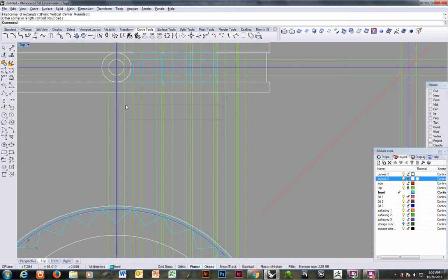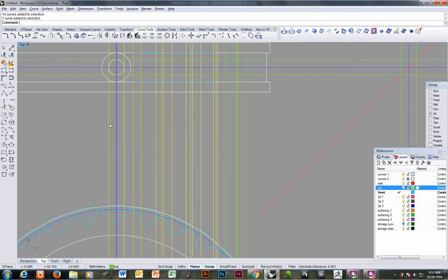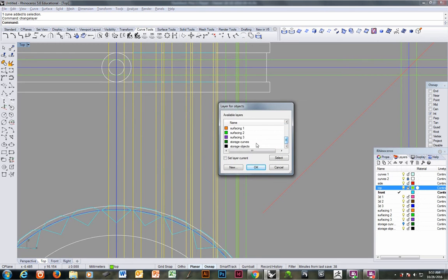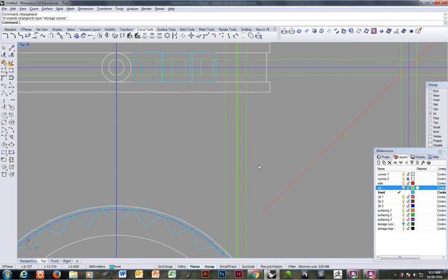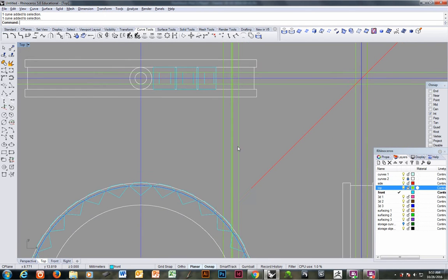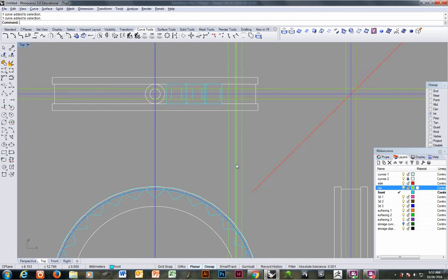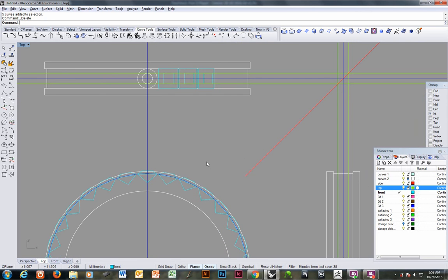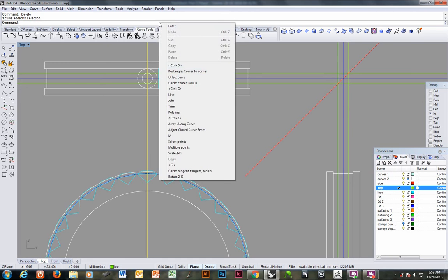Okay? I'm going to take these construction lines. Need to unlock them. Going to do a crossing selection. Take these construction lines, put them in storage. Okay. And I can take this construction line. Oh, I'm still going to need that. Alright, so I'm going to delete these for now. I'm going to do these one stone at a time now to make sure I don't get confused.